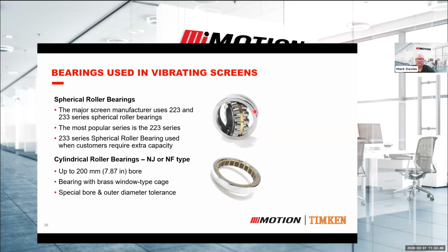But commonly in Australia, we use the 223 series and 233 series, but by far the most common is the 223 series. So when we actually specify a bearing to be used in a vibrating application, we control different parts of the design, both the cage and also the inner ring design, but also the dimensional control that we have to put onto the bearing to make sure that it works in that application.